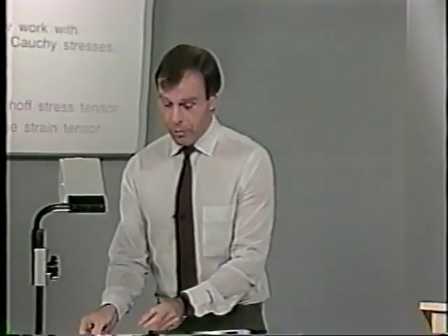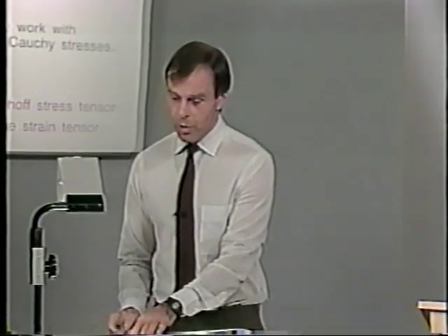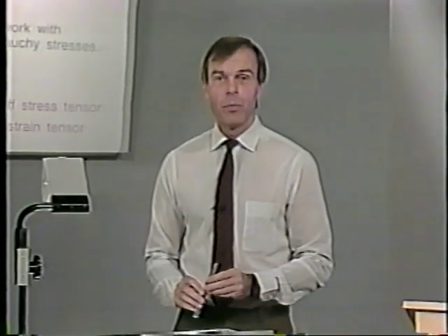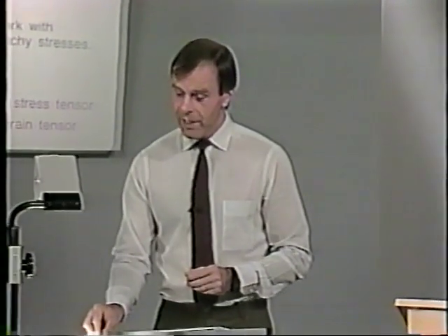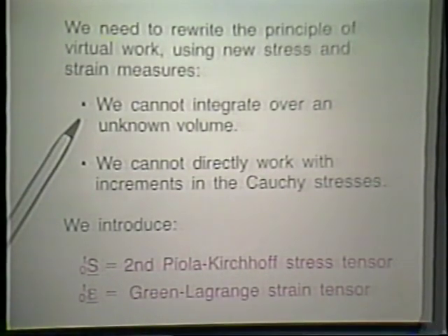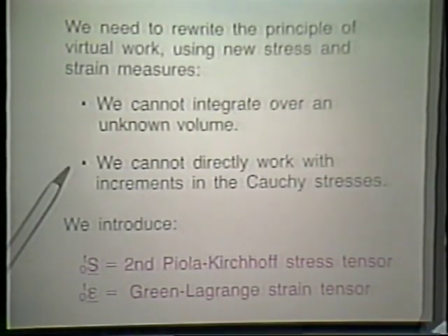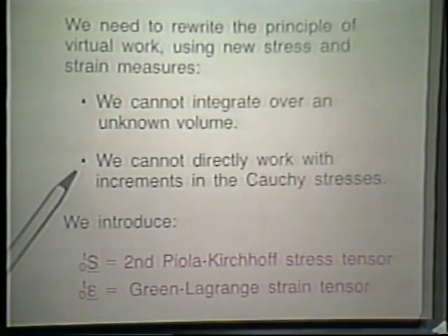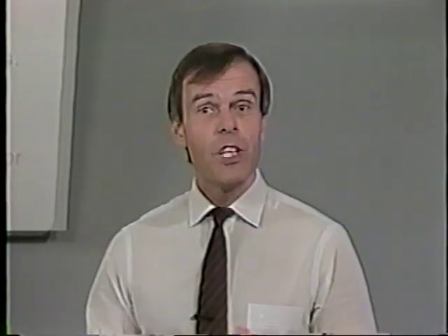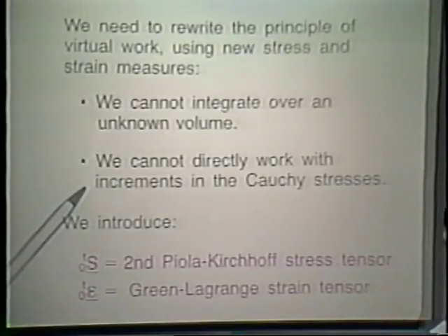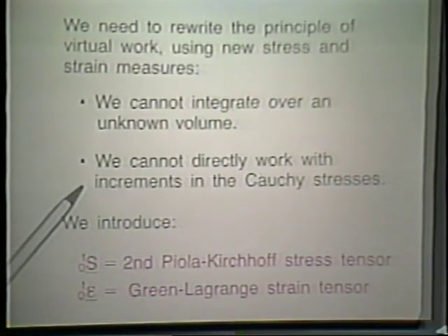In order to work with the principle of virtual work, we need to rewrite the principle really, because we cannot integrate over an unknown volume, and we cannot directly work with increments in the Cauchy stresses. The volume at time t plus delta t, remember, is unknown. And the reason why we cannot directly work with increments in Cauchy stresses is because the Cauchy stress is always referred to the current geometry, current configuration.